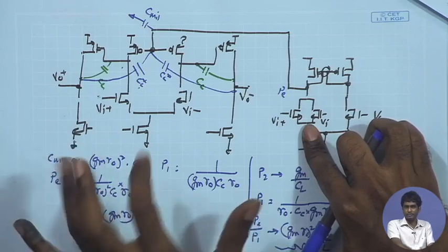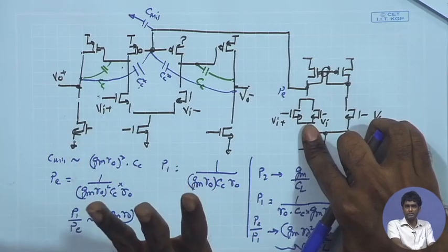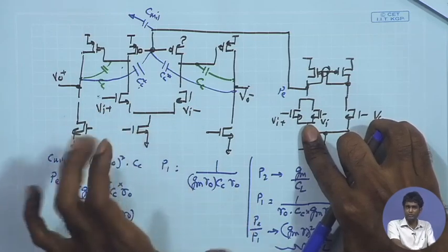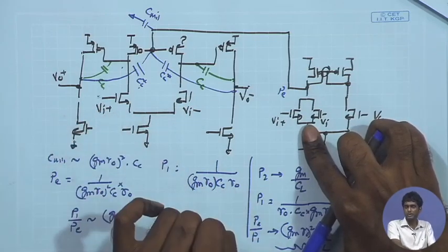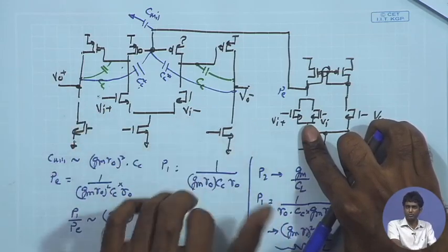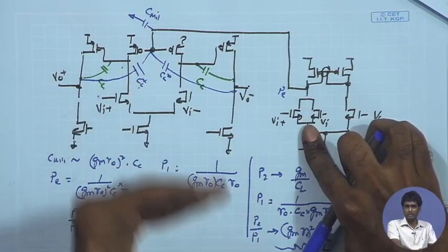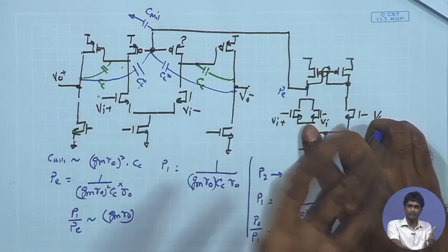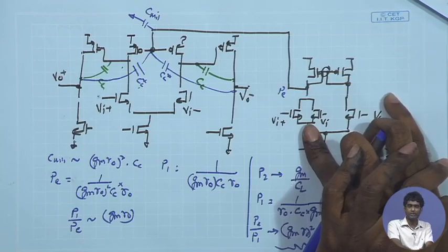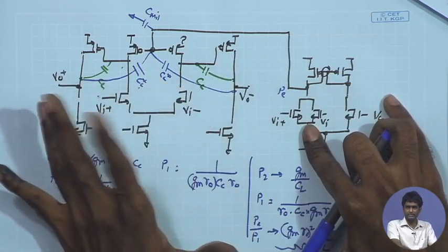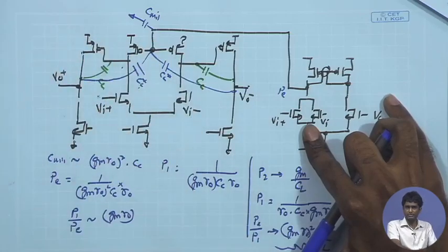So here I have just shown you so far the steps for analysis: for noise analysis this is the step, this is the sizing direction through which you can reduce the noise, these are the ways you can compensate the differential loop and common mode loop. But we need to take another example where, given these specs at higher level that we have arrived at for our front end amplifier, we see how to arrive at these values of CC, CC star, or the sizes of these transistors.